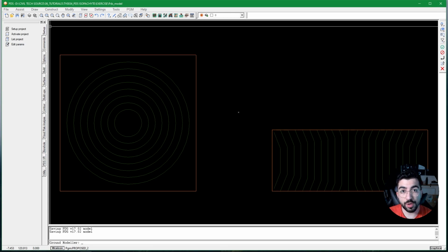And then on a new clean PDS file, I'll do all my earthworks. Because when you do the earthworks exercise, you basically just need the ground model. You don't need lines or strings unless you're using boundaries, so you can do a cut and fill within that certain area. Then I'll still do a clean Earthworks PDS file, and I'll import in the zones, let's say, that I want to use the cut and fill for.